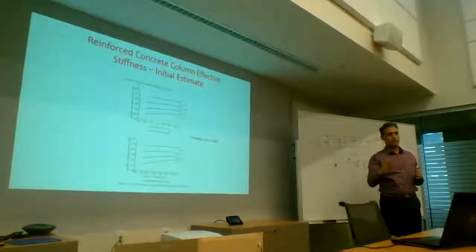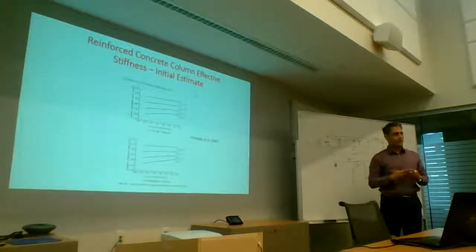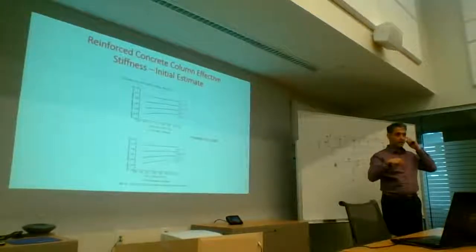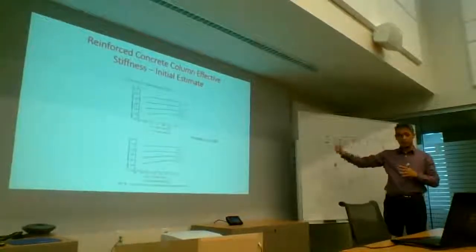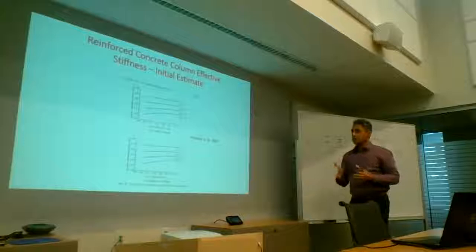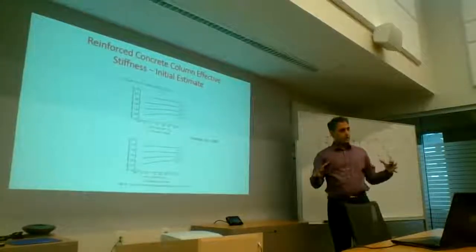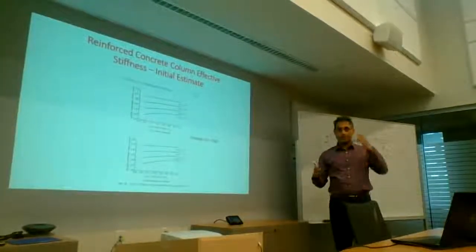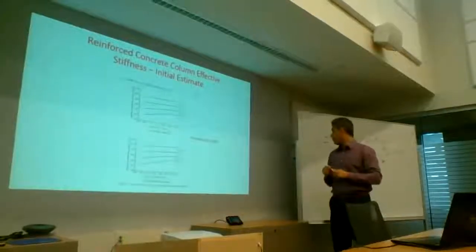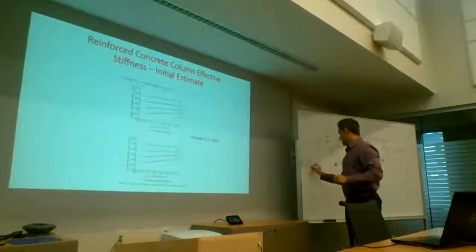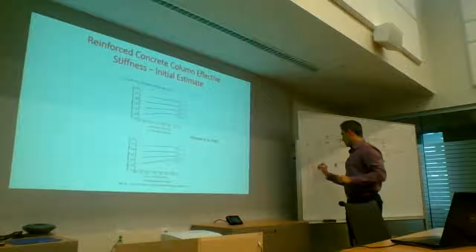At 2.5%, now you're starting to push the system in terms of rebar congestion and being able to vibrate it. So at that point, you might want to look at a slightly larger column. Don't oversize it too much. And you want your system under gravity load.